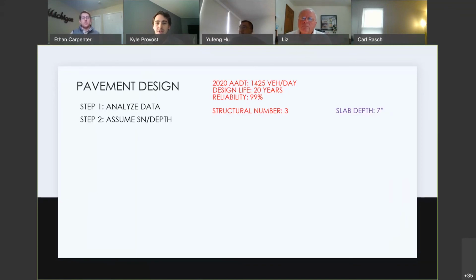HMA has an assumed application rate of 110 pounds per square yard for a 1-inch thickness. Therefore, these minimum application rates will not represent our HMA depth because when combined, they are well beyond our minimum calculated value of 3 inches. Our HMA depth is now 1.5 inches for the top course, 2 inches for the leveling course, and 3 inches for the base course.